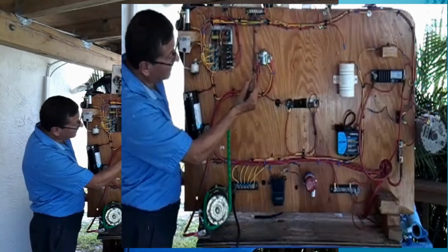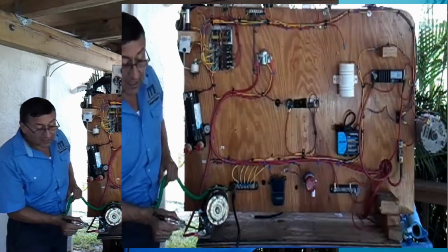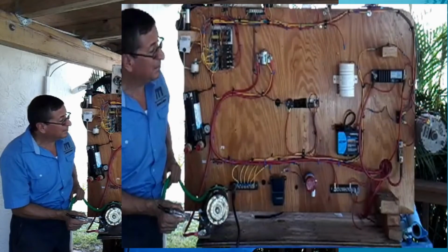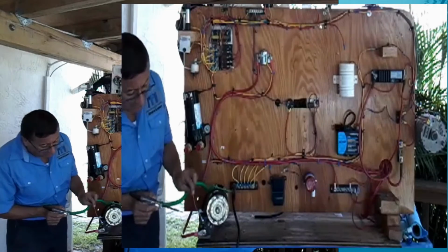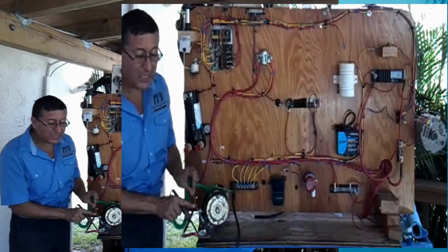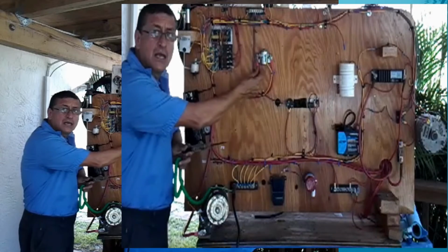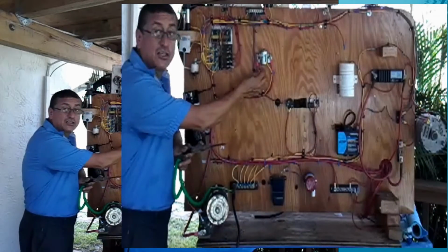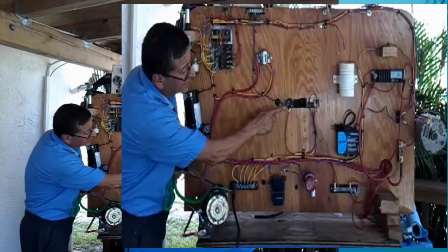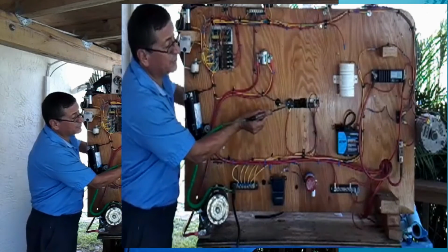Right now, when the relay is activated, I have power here at the input of the solenoid. But I don't have power in the output because I don't have signal here. What is the color code for the signal on the solenoid of the start motor? Yellow-red. What is the color for the signal on the start relay? Purple. The purple signal is coming from ignition, from this position, and the yellow-red signal is coming from the start position. In this moment, start is off. I don't have signal here.